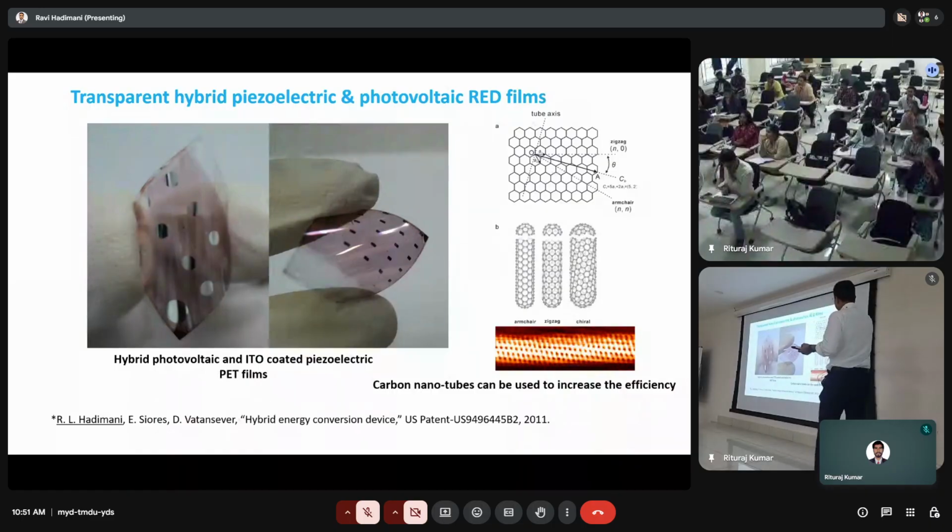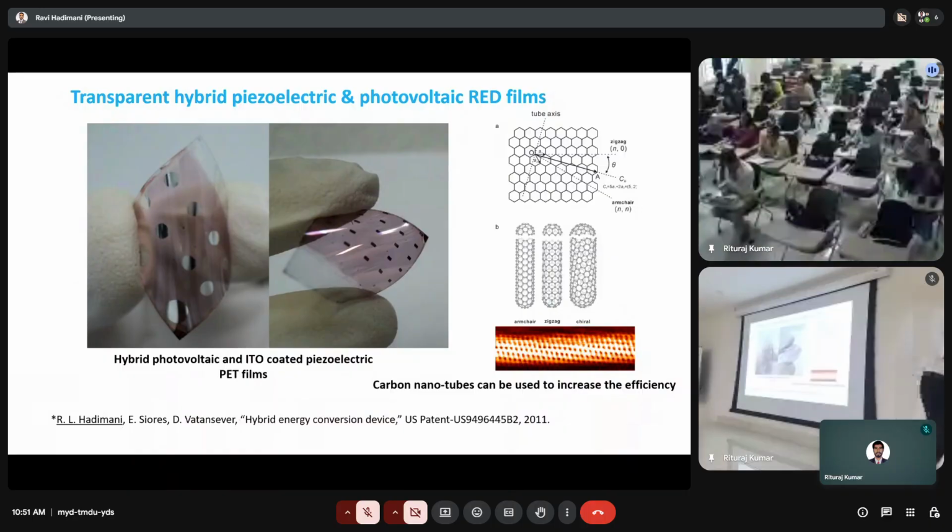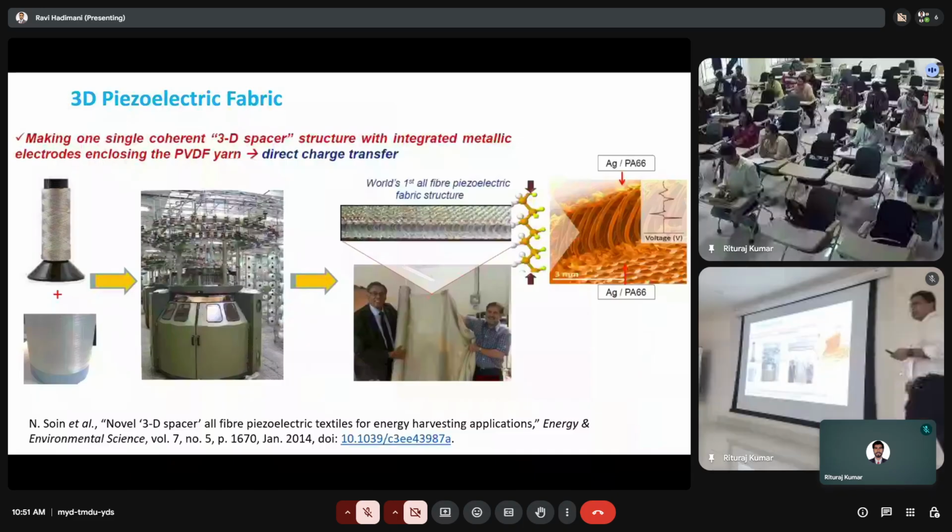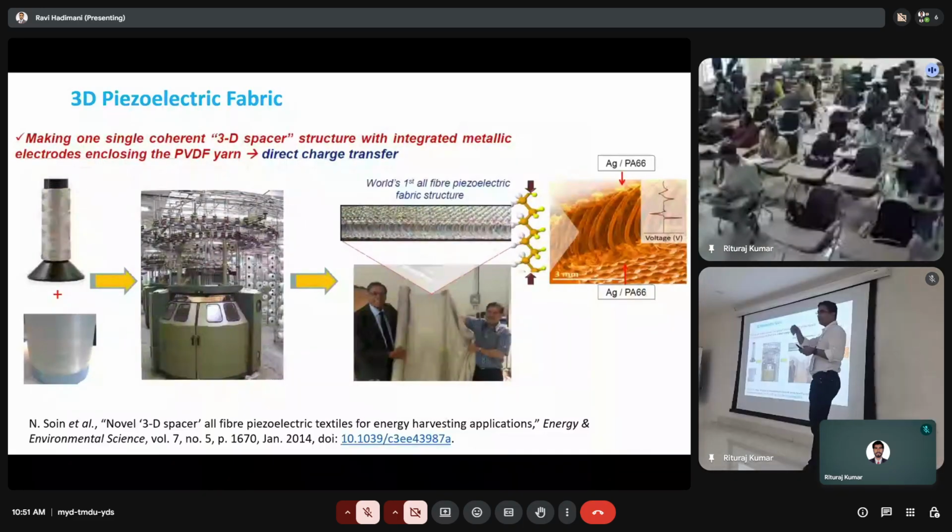So we were thinking of ways to separate them out. So that was using carbon nanotubes and so on. Again, that did not work out either, because by the time you add carbon nanotubes, the liquid becomes so viscous that you can't deposit 100 nanometers. It has to be a 100 nanometer film, otherwise light doesn't generate free electrons.